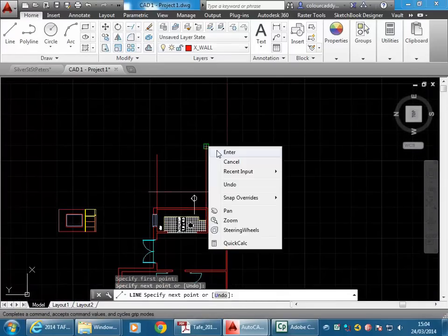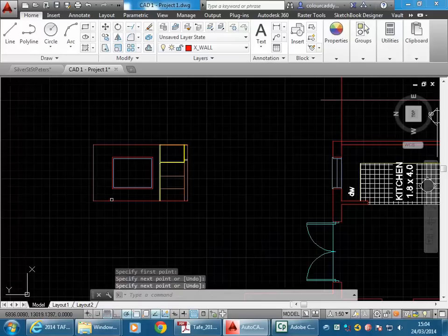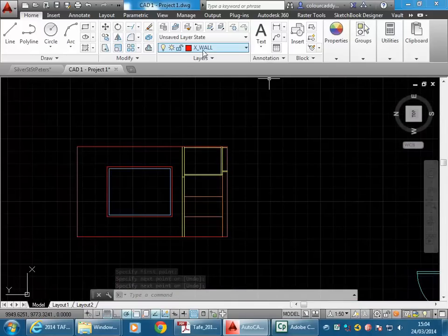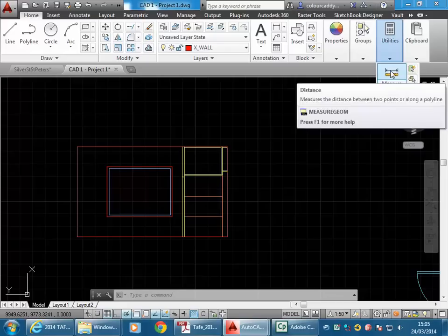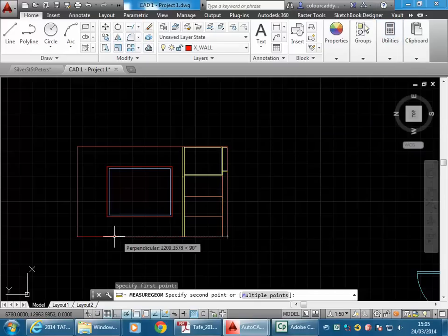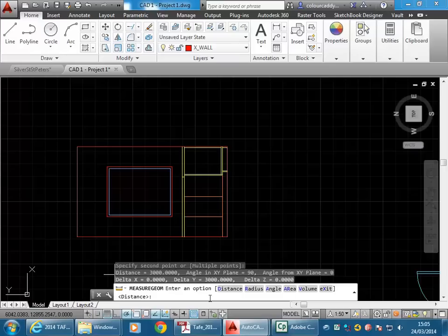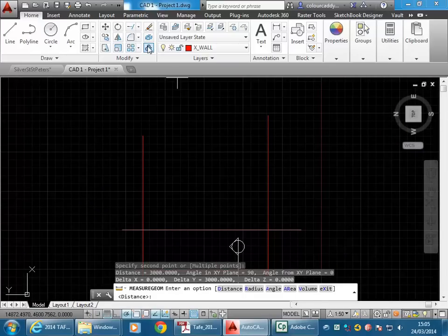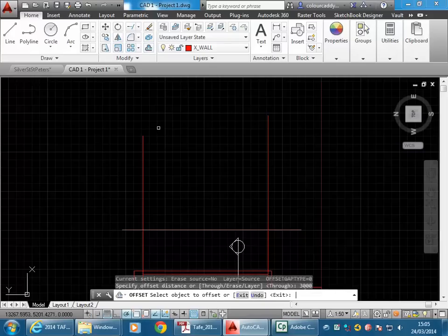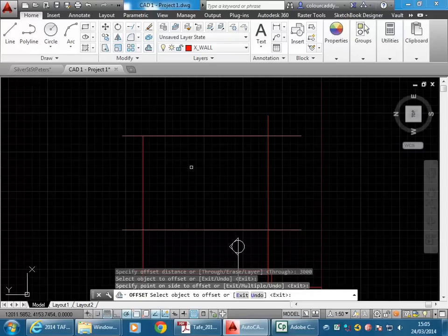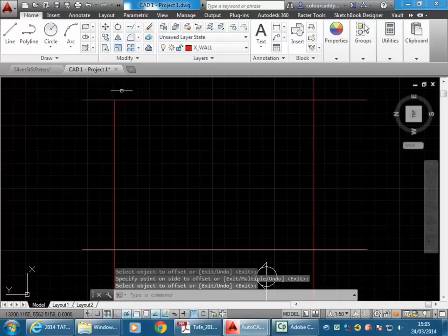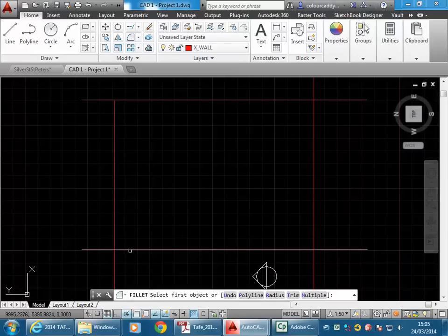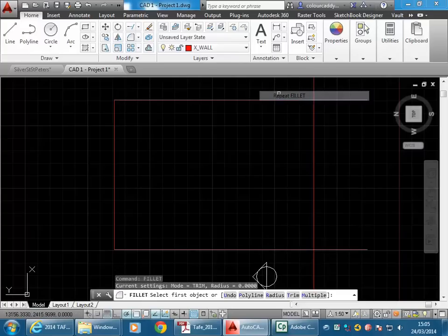Come up. We decided on a height for the kitchen last week, I can't remember it, so I'll just measure that. Now, measuring the corners on this elevation, and it is probably 3 metres. Yep, 3 metres. So here I'll offset 3000 to get the ceiling. And so now just with fillet, I can join those lines together. Checking, of course, that the radius is 0. Really important that they do this join at a corner.